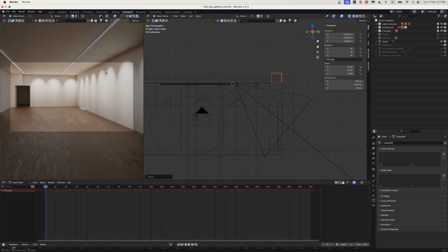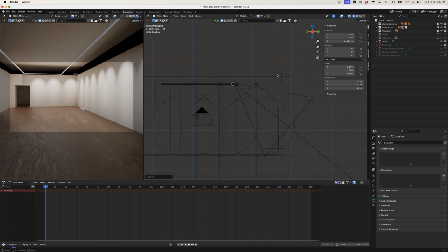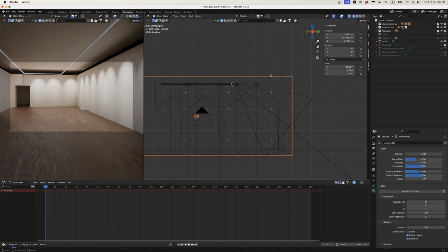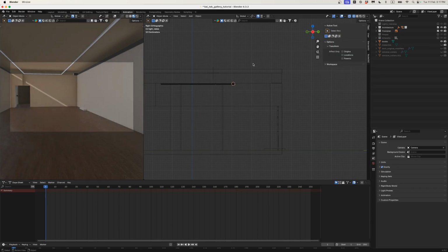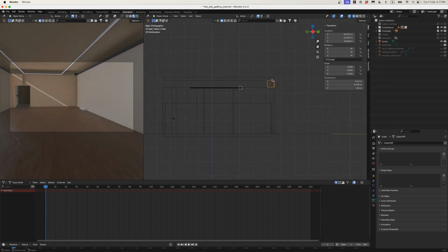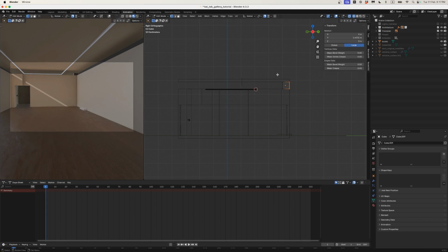And that also means I may as well just, I'm going to click on my roof here, and I'm just going to raise up my roof now to the height of my pillar. And I'm just going to now click on the pillar. Oh, my lights are turned on. I'll just go from here into material preview, turn off my lights. That's fine. Now here's my first pillar, and I'm going to go into edit mode, drag select the vertices here on the left, and I'll just GX and oh sorry, GY and snap them all the way across.